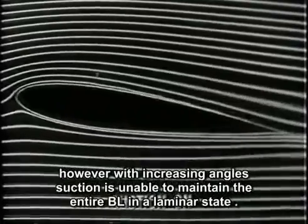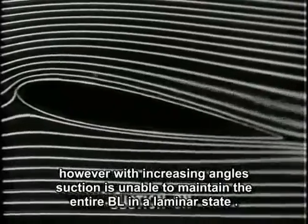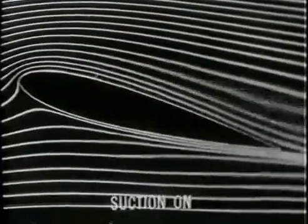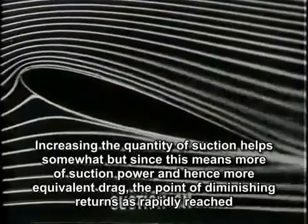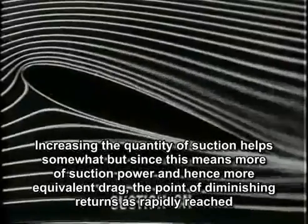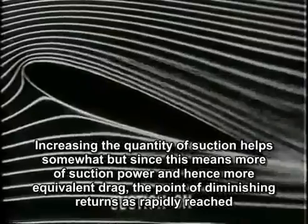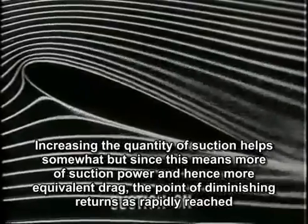However, with increasing angles, suction is unable to maintain the entire boundary layer in the laminar state. Increasing the quantity of suction helps somewhat, but since this means more suction power, and hence more equivalent drag, the point of diminishing returns is rapidly reached.